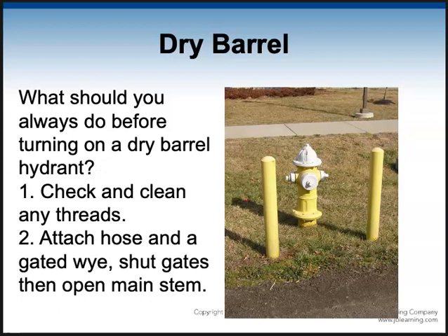First of all, you want to check and clean that you have good clean threads and attach any hose that you're going to attach. But I always say on the outlets that you're not going to use, instead of just leaving the cap on there, attach a gated Y, shut the gates, then open the main stem. Even though you're just thinking, I only need this 4-inch attached, but maybe later you're going to need more water,